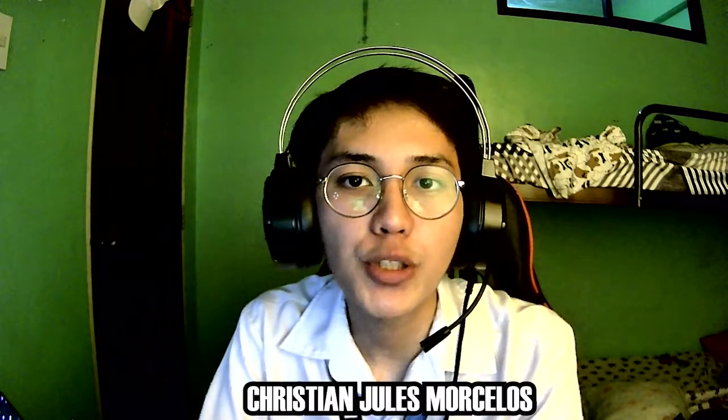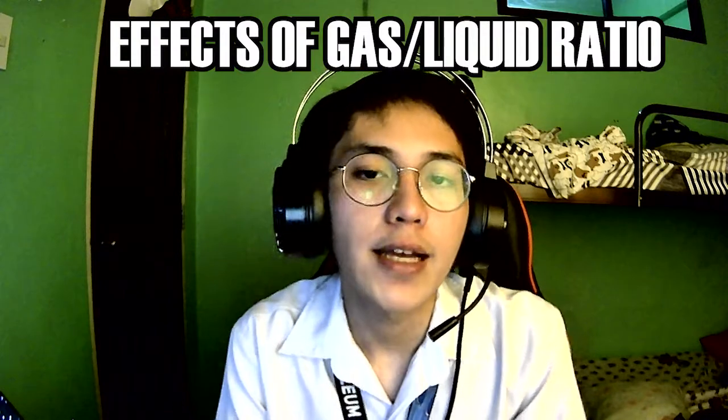I'm Christian Jules Marcelas and I'm here to discuss about the effects of gas and liquid ratio. The primary distinction between single-phase and two-phase reservoirs is that the producing GLR in the latter varies with time as reservoir pressure decreases. The density of the produced fluid decreases as GLR increases. This results in a temporary reduction in the required flowing bottom hole pressure.